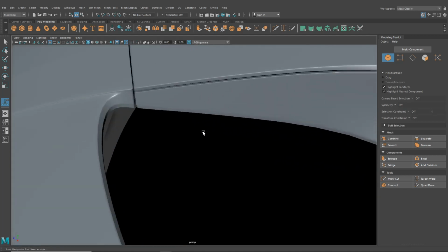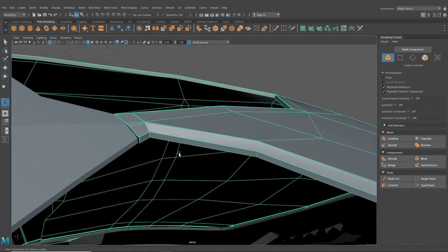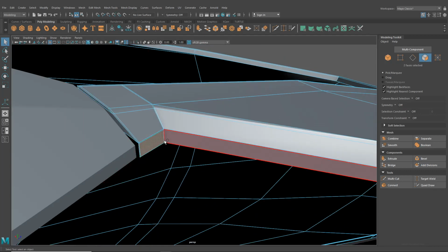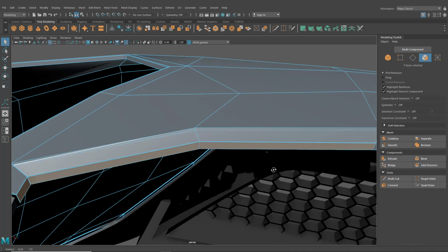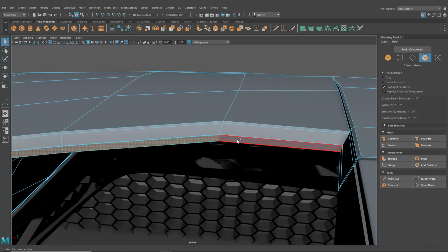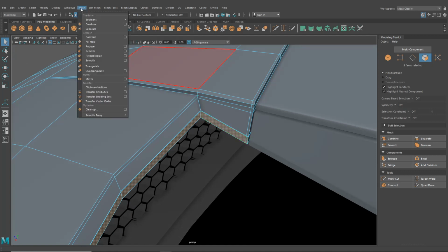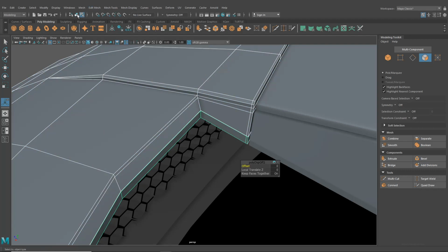And then what we're going to want to do is we're going to want to make a section that's going to be relative to this. So let's go in, let's select all of these faces. So I'm going to grab all of these here. Take all of these. I'm going to go say mesh or edit mesh, and we're going to hit duplicate on those.